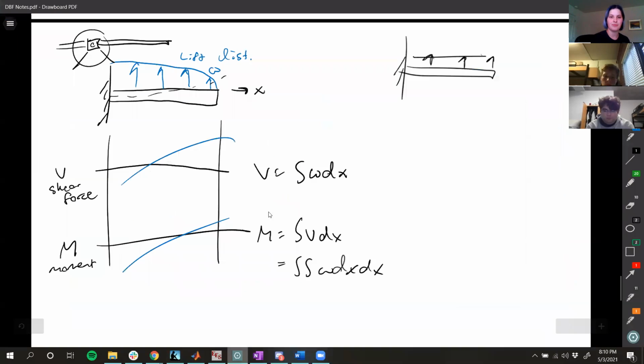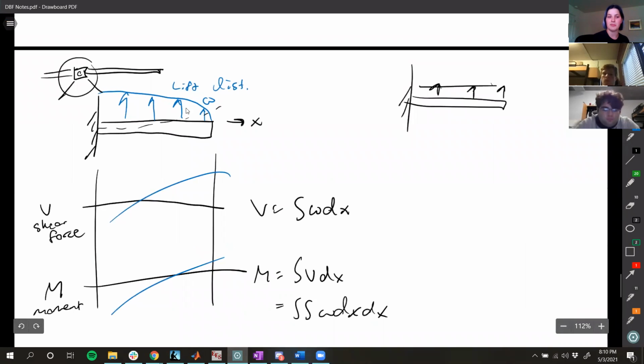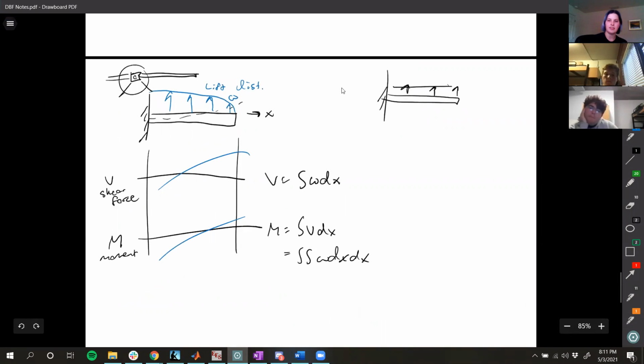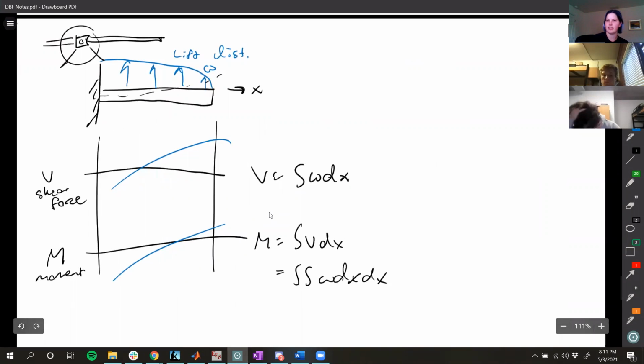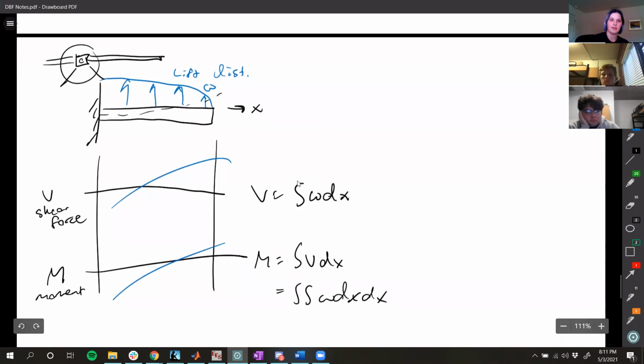So if you imagine you had a cantilever beam and you load it, it's not gonna break right there, but it is gonna break down there at the base. Unless you have some weird material, like a void somewhere, then sure, but whatever. So these are math things, and I don't particularly want to get into that because you're going to take a class on it in a little while. But yeah, that is the integral of that.